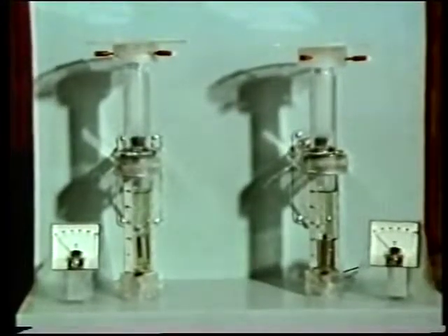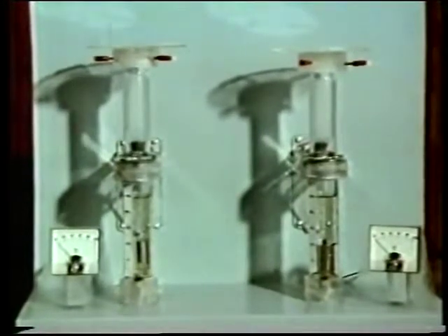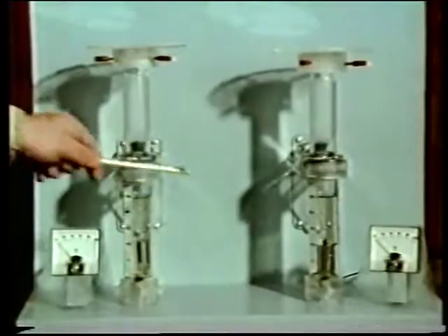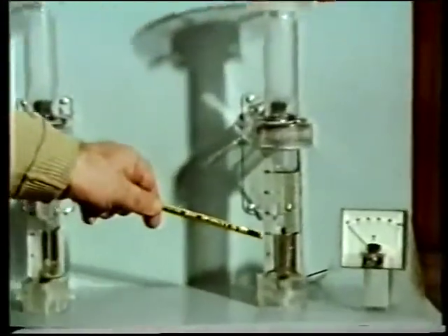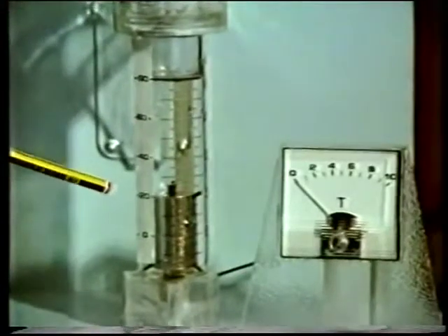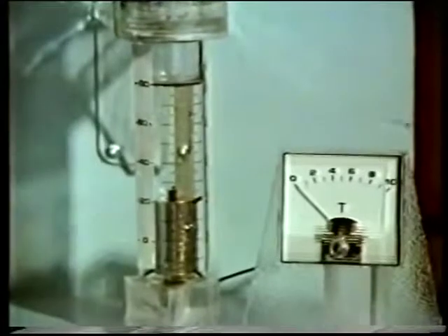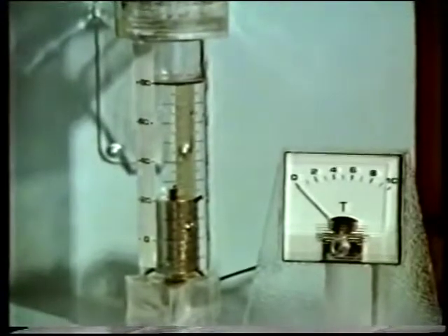Well, let's have a look at how a gas in a cylinder behaves. We're going to consider two systems of a cylinder and a piston. Both cylinders contain a given volume of gas trapped by a piston, but there's a difference. The right-hand cylinder contains a conducting object, a metal, to allow thermal energy to escape or enter the trapped gas. The volume of gas is recorded on the left, about 80, and any temperature change is recorded on the right.